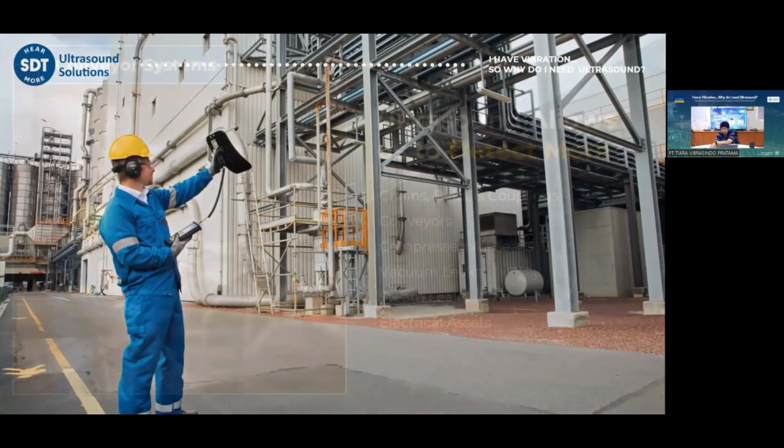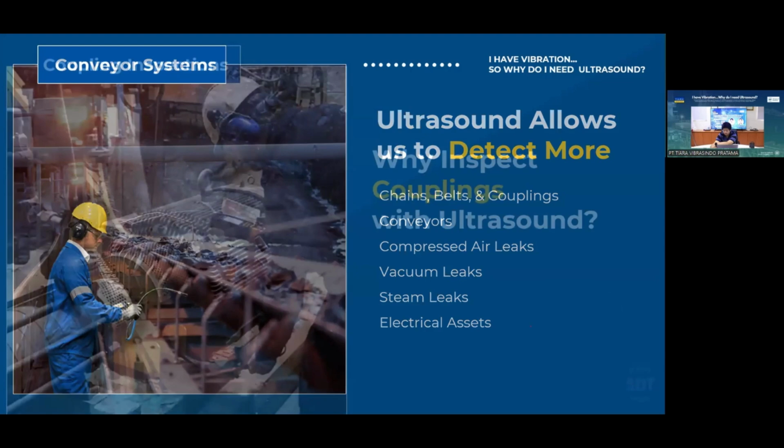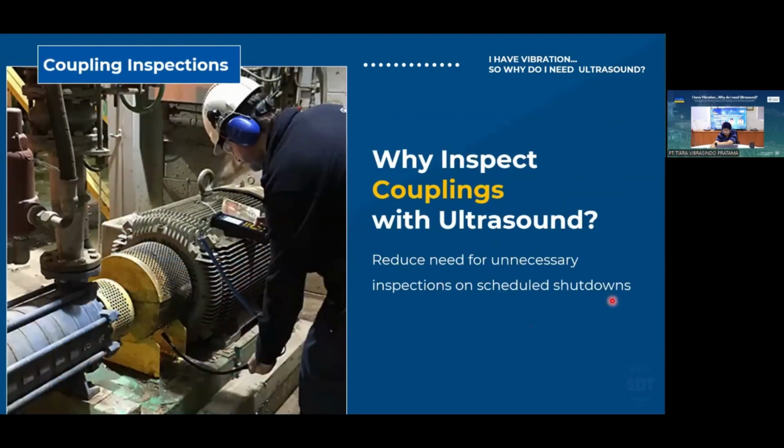Ultrasound allows us to detect chain, belt, coupling, conveyor, compressed air leaks, vacuum leaks, steam leaks, electrical faults, and valve faults. And why inspect the coupling with ultrasound? Because if you have a machine, you cannot stop it when you collect the data. It's different from vibration, because with vibration you need to put the sensor on the surface of the machine. But for sound, in this picture, we have the airborne sensor. We don't touch anything. We just measure the sound generated from the coupling. So we reduce unnecessary inspections, schedules, and shutdowns. We don't want to turn off or shut down the machine, but we can measure while the machine is in operation.